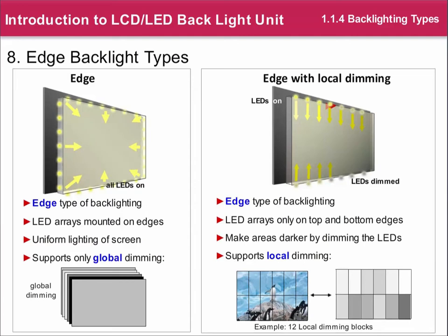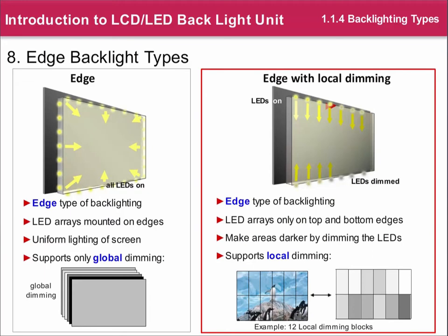But this dimming happens in a more rough manner compared with IOL, which has hundreds of fine LED blocks spread behind the screen. The right-hand example shows that the LEDs are mounted only on the top edge and bottom edge and make up 12 large dimming blocks.